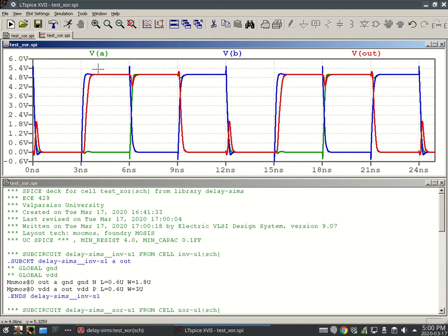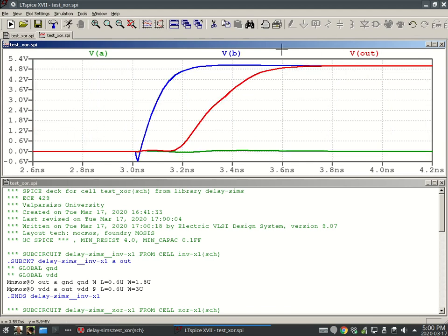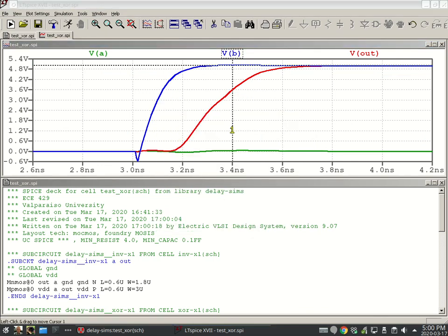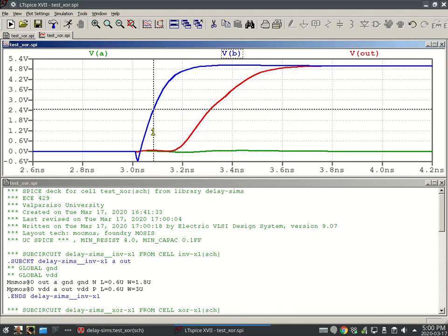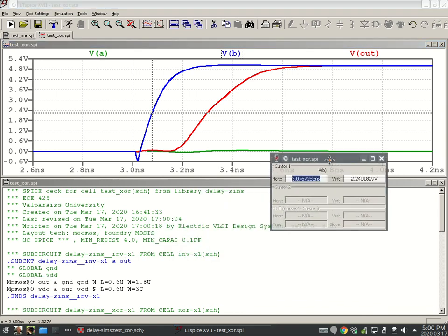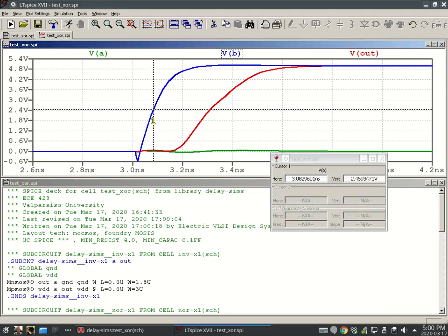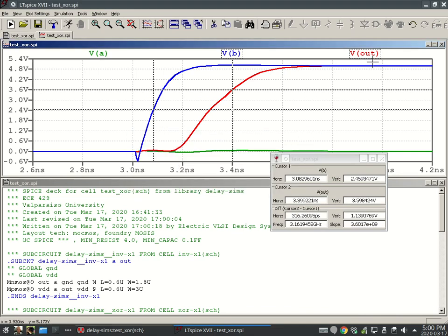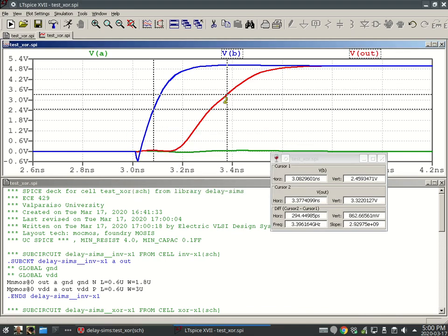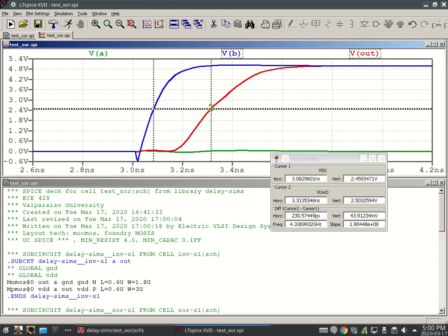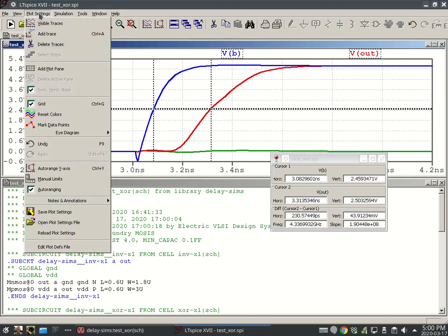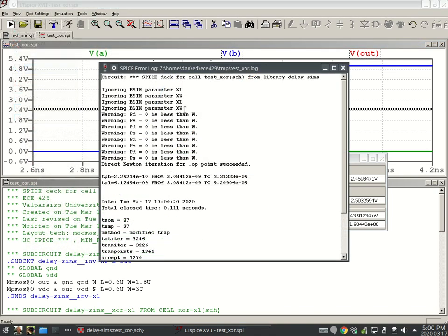Now let's measure this again really quickly with our cursors. This would be TPH, is what we called it. Oops. Cursor number 1 at 2.5. Close enough. And second cursor, I right clicked on here. It is 2.5, and we had 230 picoseconds. Remember that, because I'm going to go to View, Spice Error Log.